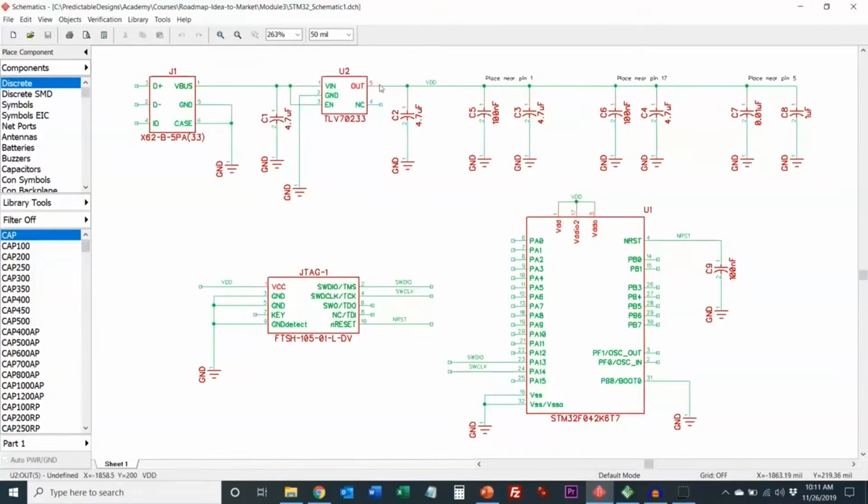The other key thing to keep in mind with the schematic, or any electronics design, is the fact that there are dozens of different PCB or schematic design software. I'm using one called DipTrace, but that's not a real well-known package. The more common ones would be Altium or Eagle. And the thing to keep in mind is a lot of these packages are not compatible with each other. It becomes very problematic if you want to switch design software in the middle of a design.